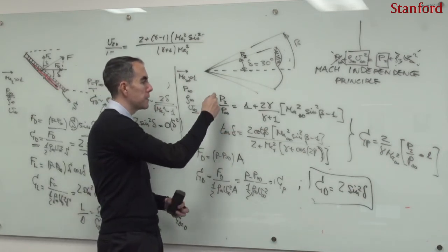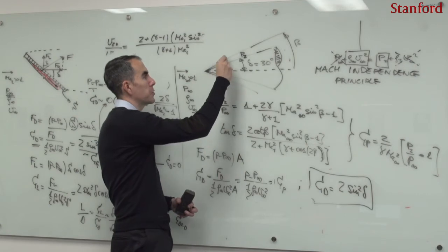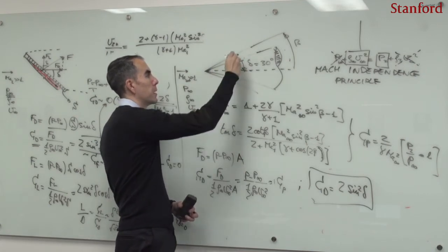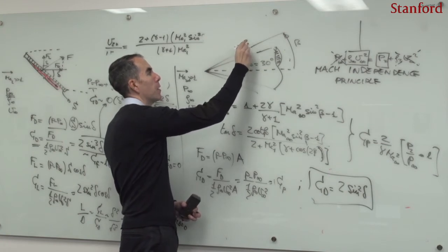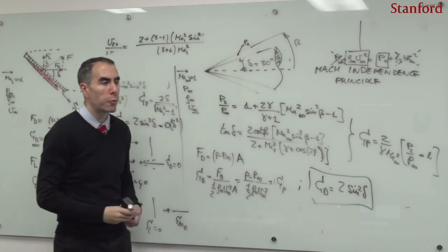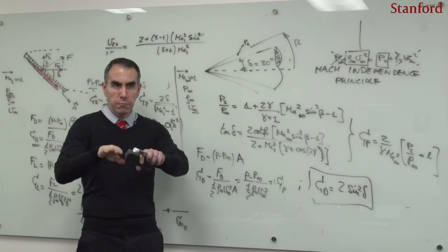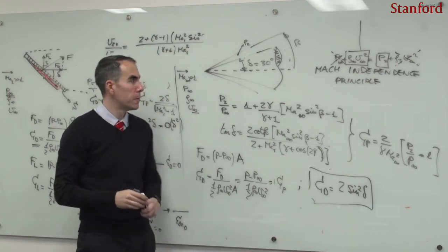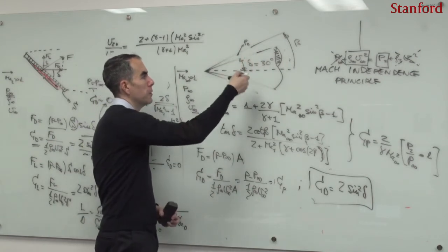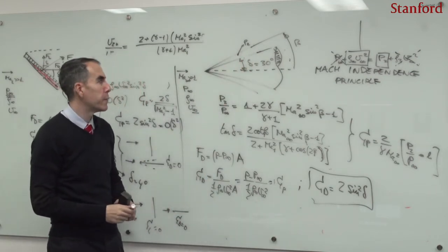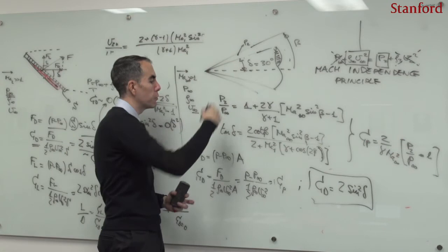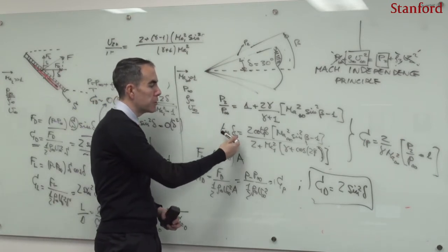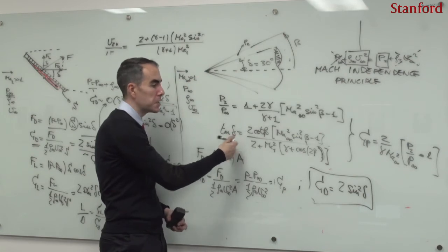And we will see that later. But in this case, for a cone, even though the post-shock pressure just right downstream of the shock, that pressure P2, is given by the Rankine-Hugoniot equation, the azimuthal curvature of the cone, in this direction, generates a pressure relief, and that pressure relief effect is actually two-dimensional, in such a way that this expression here for the tangent of delta, if I attempt to solve this expression,